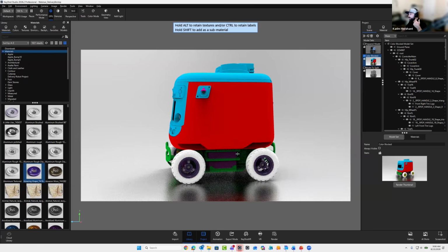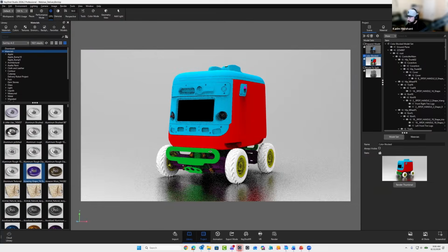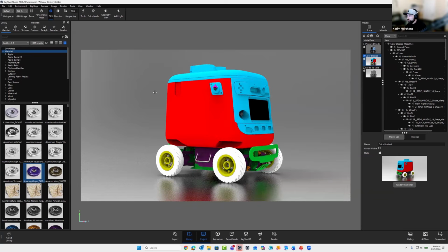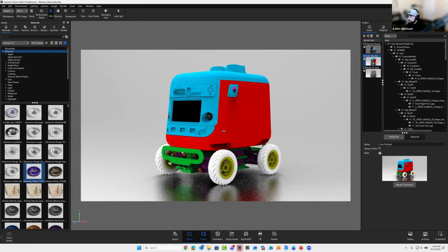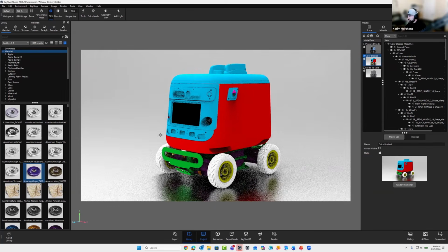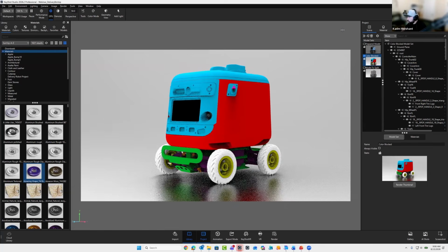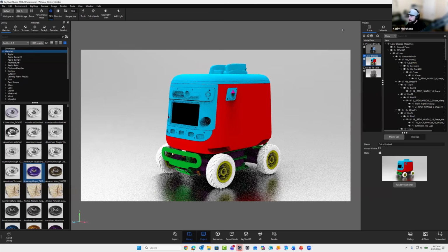Now, if you are a KeyShot user, you maybe have a product catalog where you're using similar materials over an extended period of time, or you have somebody updating those materials based off of trends or whatever you're following. We do have a tool called the material template tool. If I have CAD data and I know that I'm going to have certain materials applied, I can create a material template. I'll just go ahead and create one real quick. You can add different parts and materials manually if you want specific ones to come over. In this case, I'm just going to use automatic and hit material.